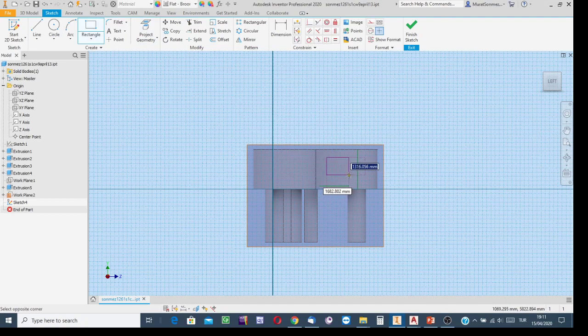So create a rectangle and then the location dimension relative to the floor for the lower boundary of the opening is 900, let's say. Okay, and from here to there the distance is 600. Okay, and the width of the rectangular window is 1600. Okay, height is equal to 1000.